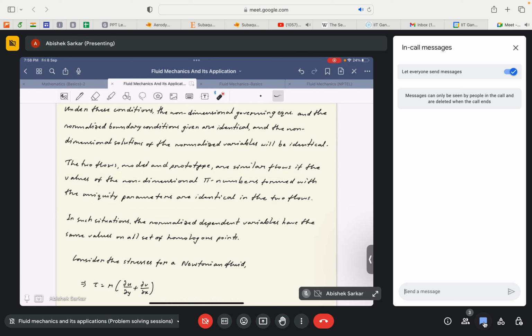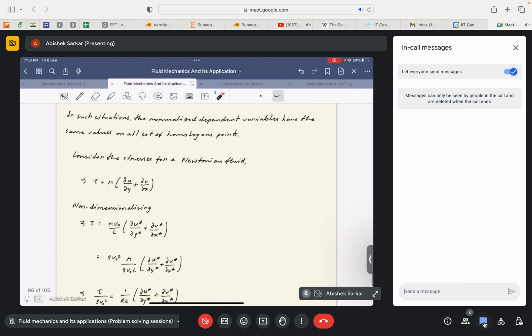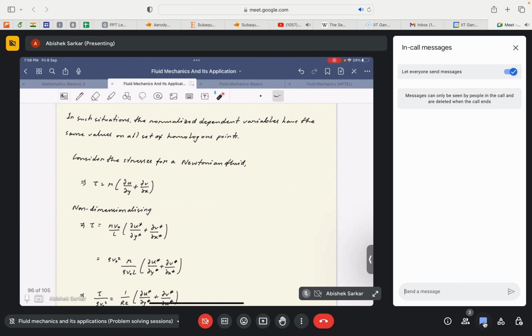So ideally, it is better if we could find ways to discard the non-dimensional numbers that can be discarded by disregarding the factors that do not play a significant part in driving the flow, right? That is where the concept of the driving factor of a flow field comes into the picture. So let's see a brief example of non-dimensionalizing different flow variables.